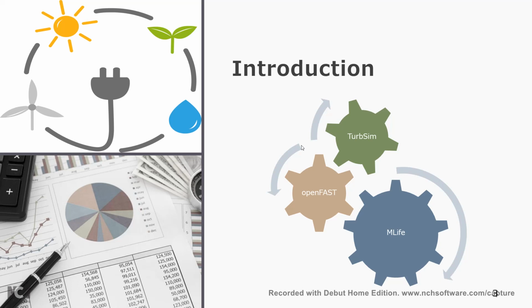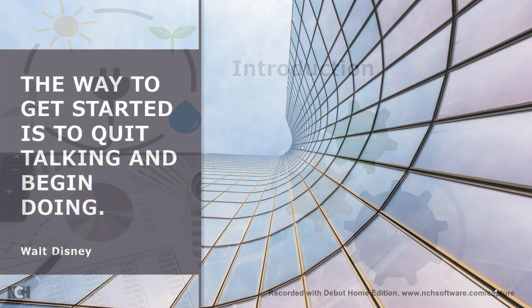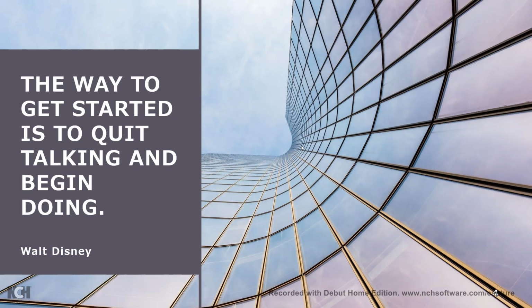And then what you do is you take MLife, which is a MATLAB program, and feed it all the data from OpenFast, and it will calculate fatigue and life and something called DEL, which is the damage equivalent load. So, the way to get started is to quit talking and begin doing. Great quote. So let's quit talking and let's actually do something.